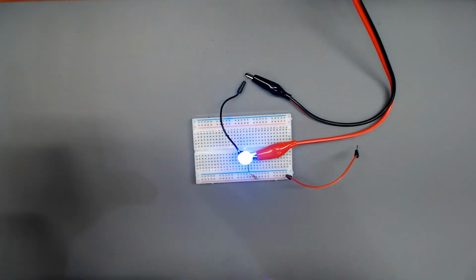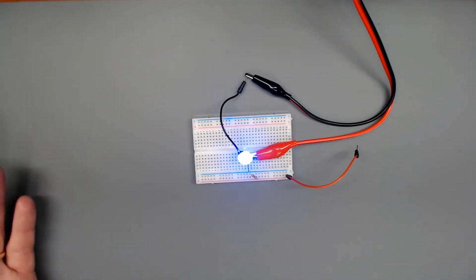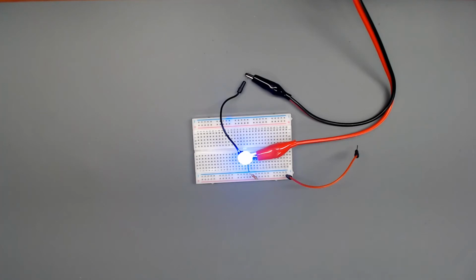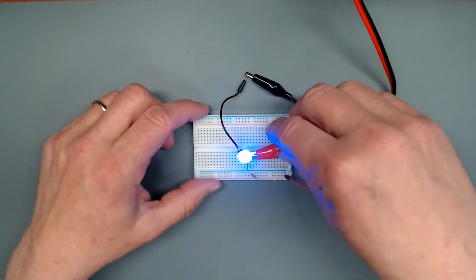It's not hot. That's because the forward voltage matches the supply voltage. It's when our supply and forward voltages don't match up that we've got to limit the current. In this circuit, everything is, we'll call it, self-regulating. However, that's not what I recommend even for a blue LED.